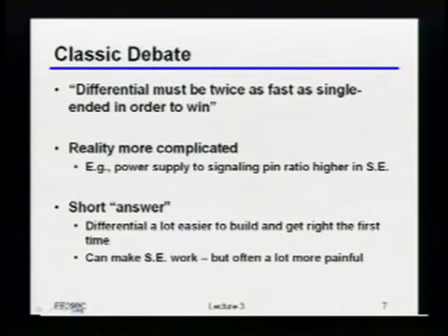So I wouldn't claim that I necessarily know the answer there. But if you force me to give an answer, and of course, since we're taking a class, I'll try and give you some answer that I think makes sense. The short, quote-unquote, answer there is just that it's a heck of a lot easier to get a differential link to work. Okay, so if you do things reasonably well with a differential link, you can be pretty confident that you can stick it into most systems and it will actually work the way you expect it to. With single-ended, not really the case.